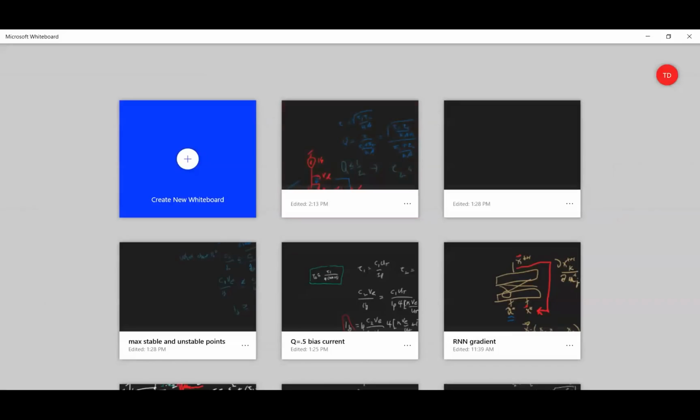Yes. Okay, good. Okay, so you have that photoreceptor, right? I'll start with this photoreceptor. And there's light shining on it. And then there's an amplifier. Let's just draw it like an inverting amplifier for now. Okay, that's the thing you guys just simulated. Nice logarithmic photoreceptor, nice and fast, low noise. It's a good front end, right? Gives you a logarithmic voltage that changes with a photocurrent logarithmically. So you get big dynamic range, like a factor of a million in photocurrent. Easy to achieve, 120 dB.